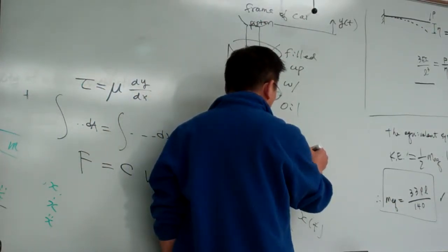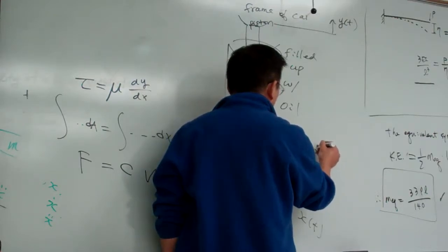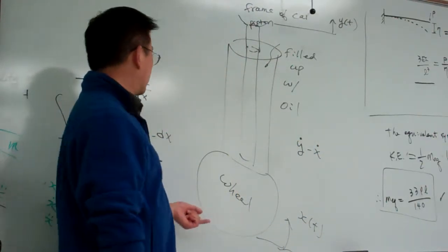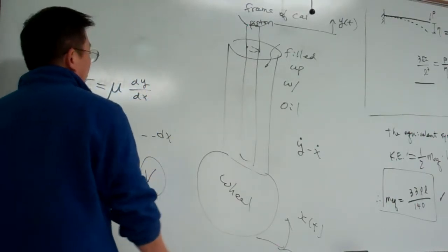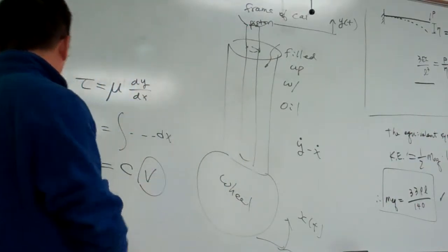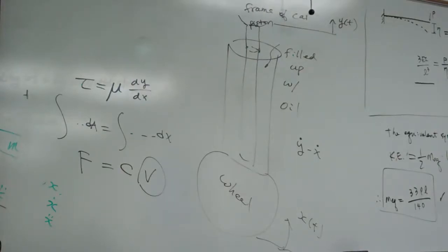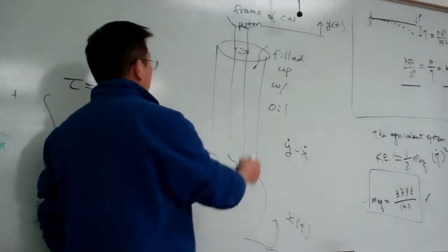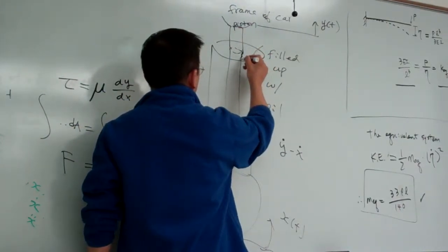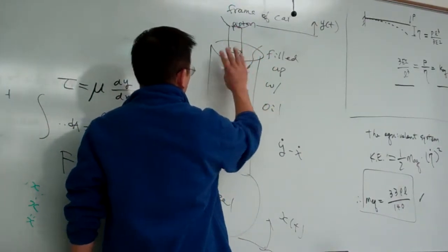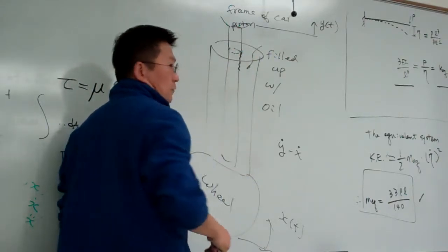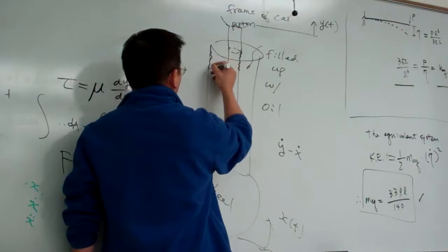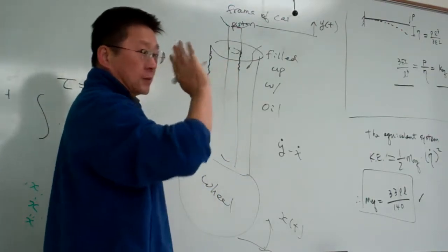So they simply take a relative displacement. Actually, they take a relative velocity. That is a term here. And C is determined by this term, A mu over D. What is A? A is the contact area. You can assume that is the circumferential area of the piston, for example, or you can approximate the circumferential area of the piston there.